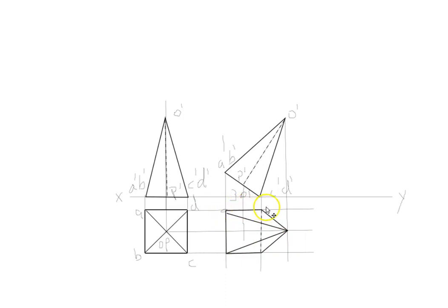Initially, after locating your points, give slightly more pressure with your pencil when you draw these outer bounding continuous lines, and with light pressure you can draw the projection lines. That is one method. Another method is to use 2H and H pencils. These are some things which will be taught in class.